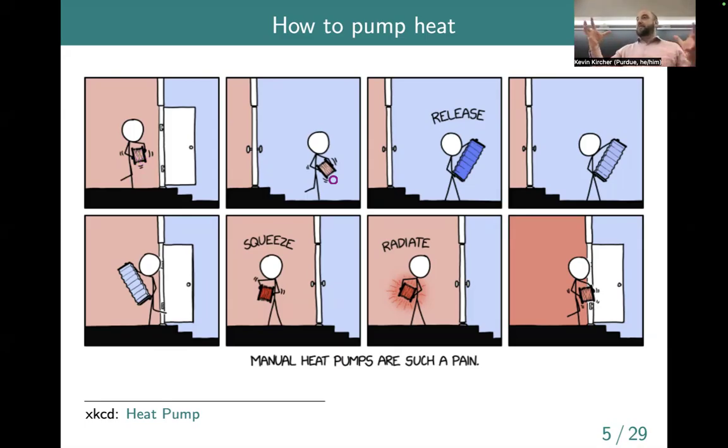So it would do some boundary work on the surroundings or on the person. As it expands, it cools down if it's an ideal gas. And so here, dark blue means really cold, and blue means pretty cold, basically. And so now we have a super cold working fluid in pretty cold outdoor air. And so there will be a heat transfer input. So even though it's cold outside in the middle of winter, say, we would still absorb some thermal energy because this is warmer than this. So we would get some conduction or convection heat transfer into the working fluid here.